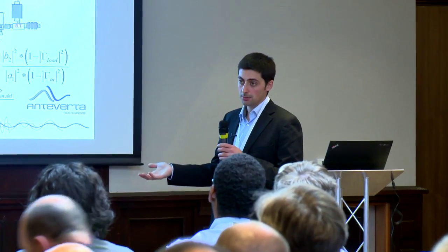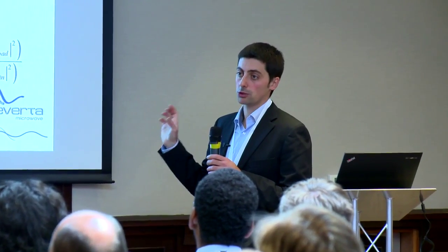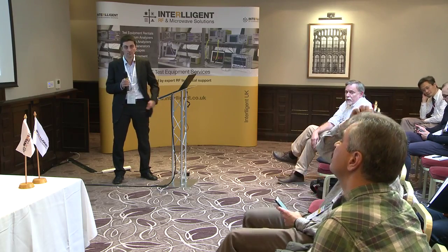You have a power calibration in order to measure absolute power. And to measure time domain voltage and current, you have a phase calibration. So you use a phase reference device. You have a polyharmonic input source to calibrate the phases. Yeah, I forget what they call it. Well, phase reference device. So yeah.